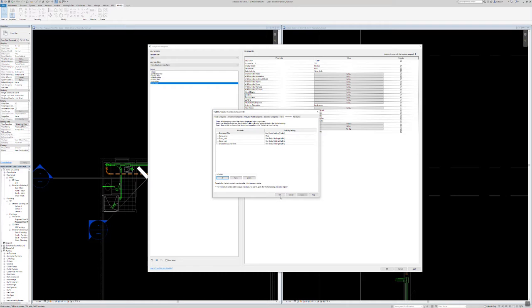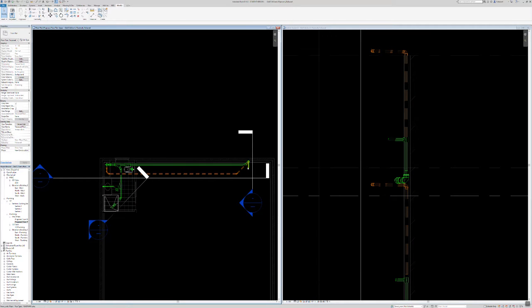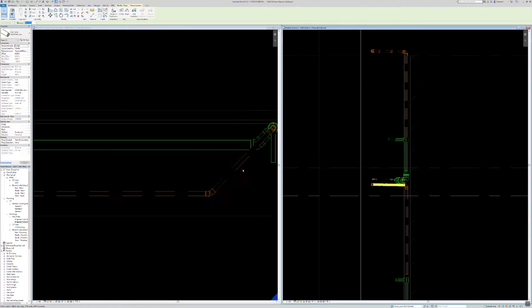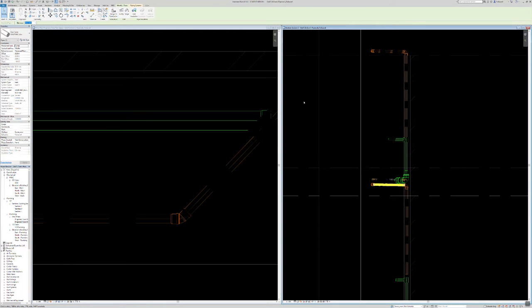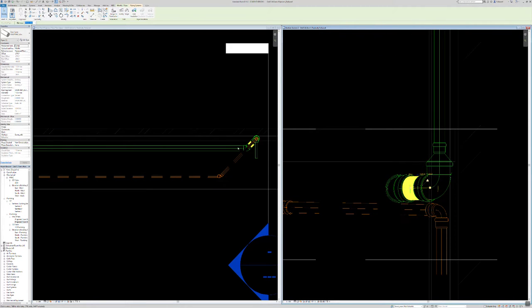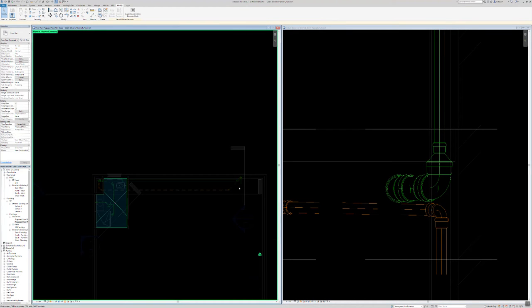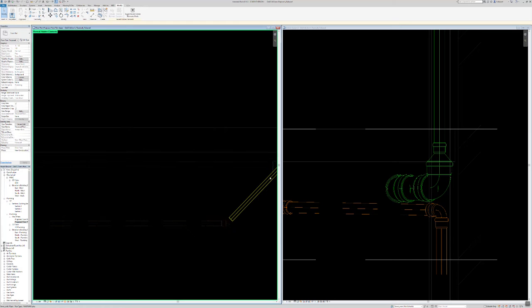Just so you can see what I'm talking about, we'll turn that on, say OK, and apply. Close that off. Now people say, oh, that didn't really do much, Mick. Well, I've highlighted the same thing that we saw before, but look, now it doesn't even show up. It's not even highlighting. And to prove it's not trickery, it's not hidden, we can do RH, which brings up all hidden, and as you can see, nothing.